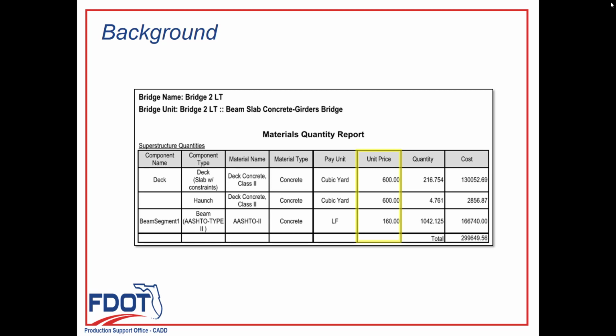When using the materials quantity report, you should also keep in mind any unique geometry that did not have a completely accurate template used or may have required workarounds, such as a squared off acute end bent corners. For example, if you model them with sharp edges rather than squared off, that is how it'll be reported in the quantities. Also keep in mind that any elements created using solids modeling rather than the OBM templates will not be shown in the automatically generated quantity reports.